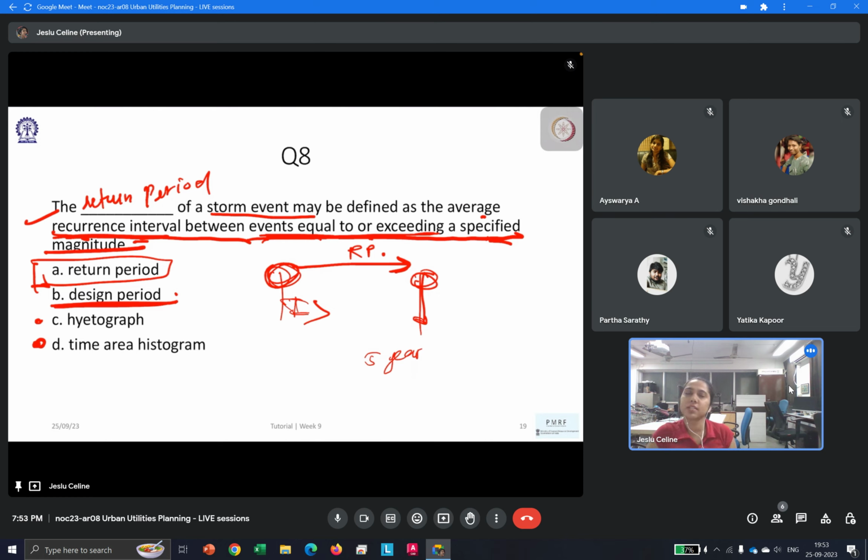So this we have discussed. For instance, if it is pumps, usually they have a design period of 15 years. And if it is other long-term planning, some facility like sewage planning, we usually say that it's for 30 years we design it for. So we design based on that. All the investment that we will be doing will be considering that this should work for 30 years.